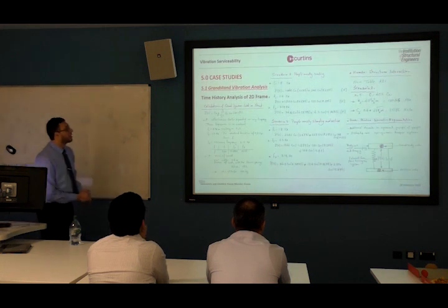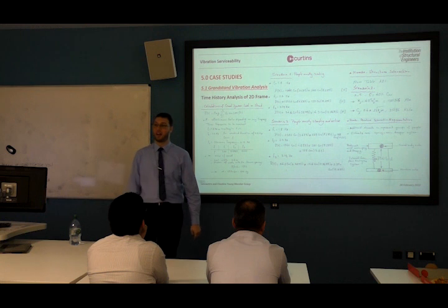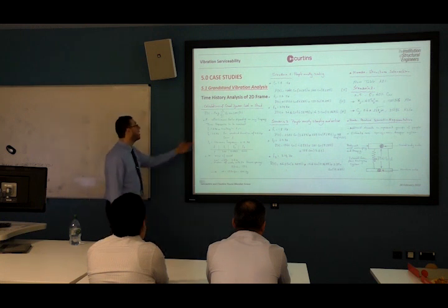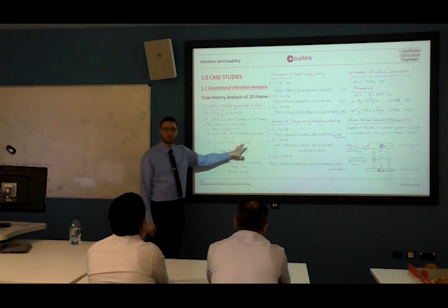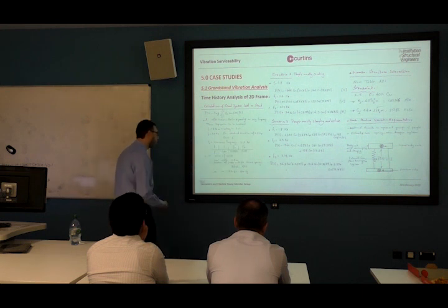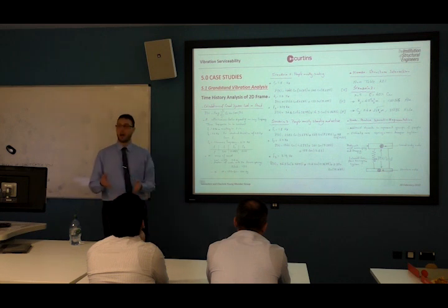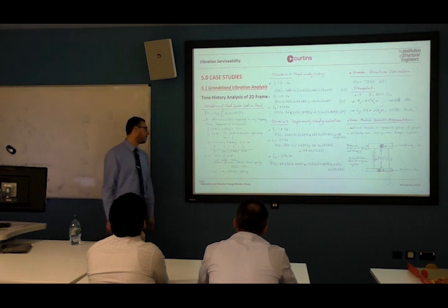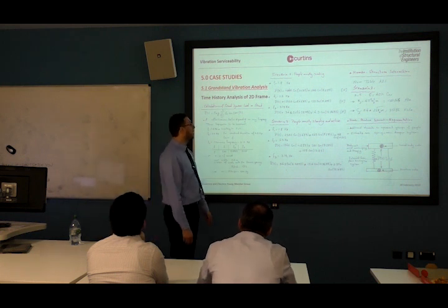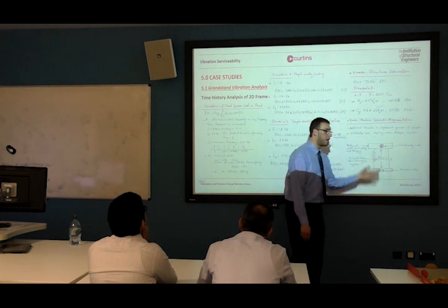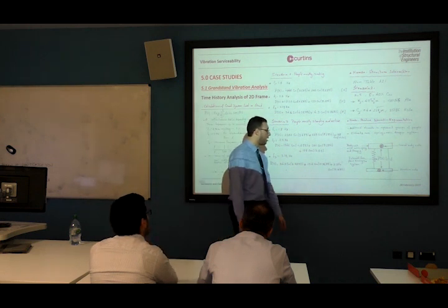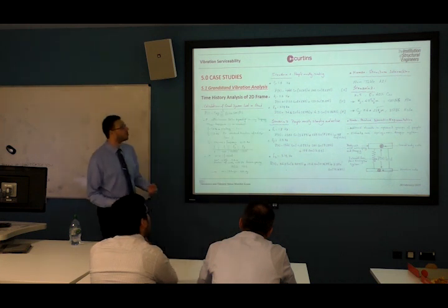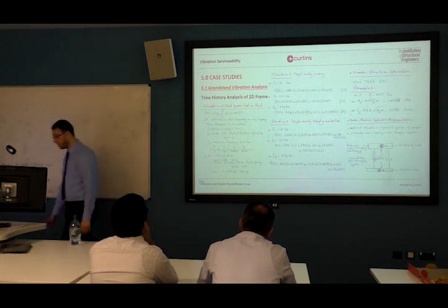So this is me doing some calculations for the dynamic loads we need to apply. Here I'm working out how much load we have to apply. The resonance value here is 3.19, and then what is the growth factor, the effectiveness factor, if you have a standard deviation of 0.5 Hz. All these values are checked. I'm also checking how much human structural interaction I need to take into account, and how much stiffness and damping we need to add to the structure.